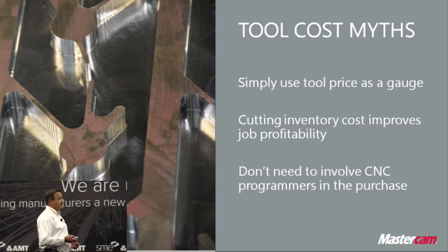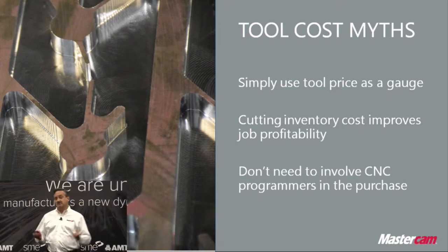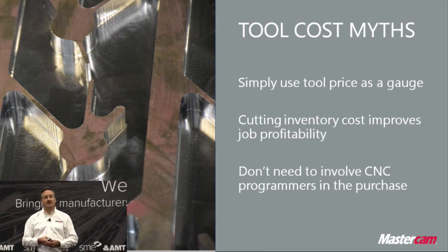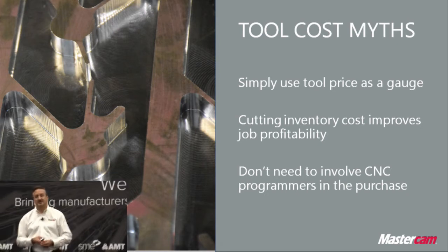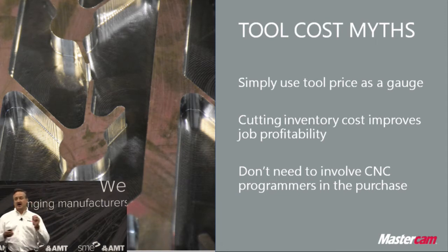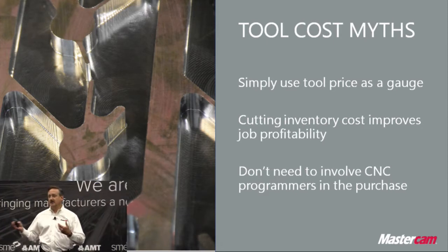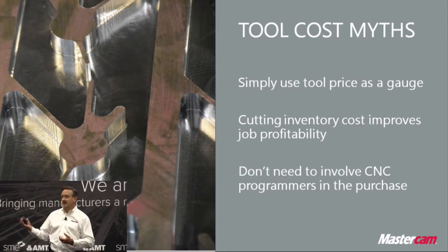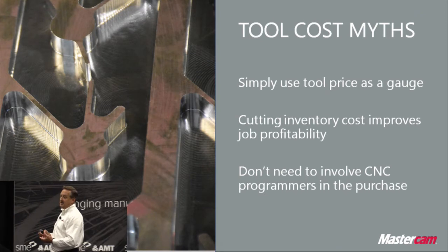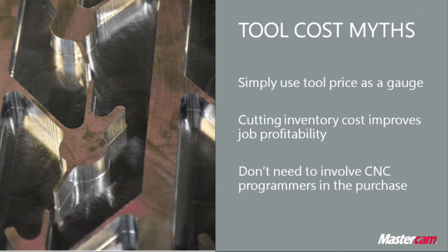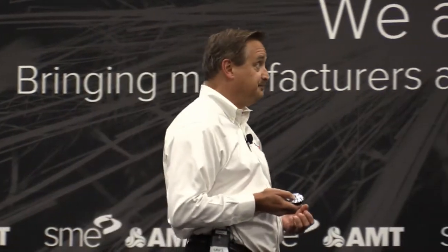Next, there's a conception out there that, you know what? You don't need to talk to your CNC programmer before you start ordering tools. And we see this a lot. Requests come in, go to a purchasing agent, they price something out, and it may not be to spec. It may not be what the CNC programmers are looking for. They go with a cheaper tool, and hence they don't get the productivity or production out that they were expecting.